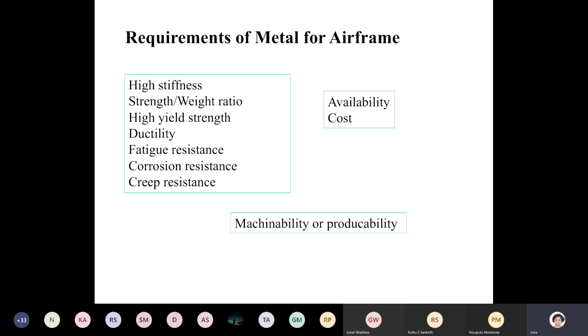The manufacturing process that is there currently is very costly, and it is not economically viable to make use of titanium in aircraft. Though titanium has much improved quality over aluminium, the strength to weight ratio is very good, the temperature resistance is extremely high, and the fatigue resistance is extremely high. But what is holding back the use of titanium, at least for fighter aircraft, is the lack of a proper, easy manufacturing process.